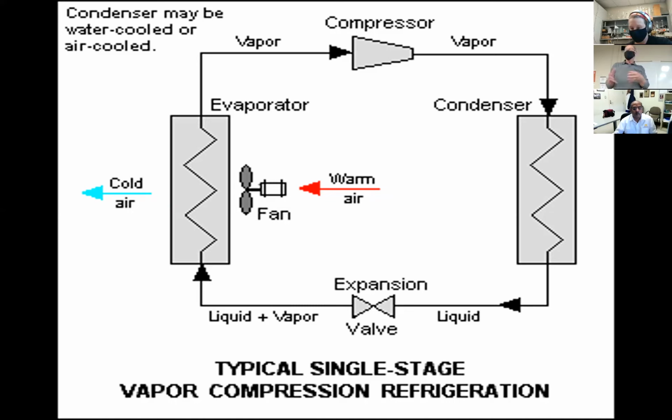compressing it down. And that's why with a refrigerant, you would like a refrigerant that carries a lot of, and ammonia is a good one, a lot of heat for the amount of volume, the amount of gas that's going through. You go from vapor to vapor, low pressure to higher pressure. The higher pressure vapor goes through the condenser, which is where we're going to give up the heat and literally condense the vapor back to liquid. Liquid flows to the expansion valve, and away you go.